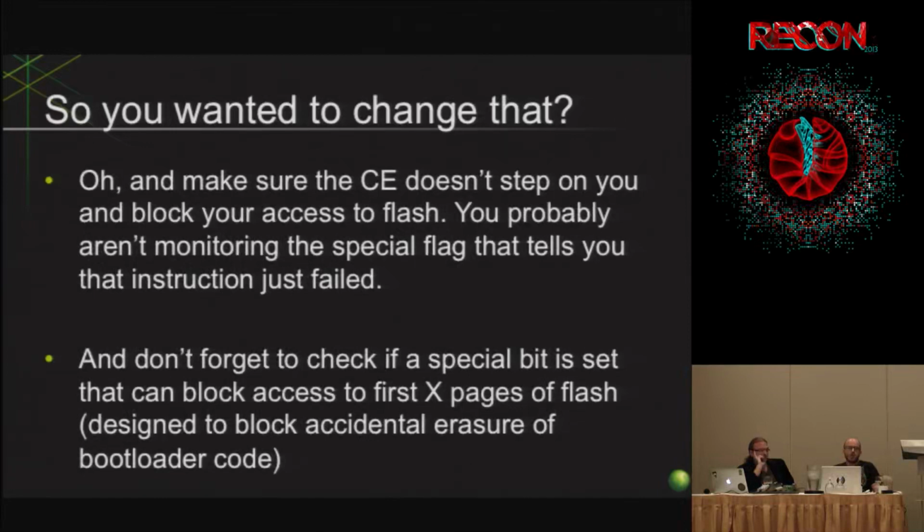There are also additional flags that are meant to protect certain sections of memory from being accidentally overwritten. One of the things that's funny, you start getting into the source code and their example code, and there are all these comments where they do their Flash updates, where they do their in-field programming. Every few lines there's some other value check where they're checking to make sure this equals this and this equals this, because they say that just natural electromagnetic interference will glitch the execution pointer, and then it'll just suddenly jump into wherever. And if it jumps into the section of program that is modifying Flash, that's a really big deal. It'll corrupt your Flash, and then the whole thing will just get bricked.